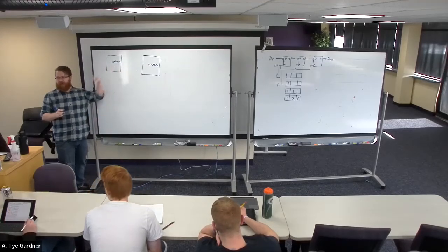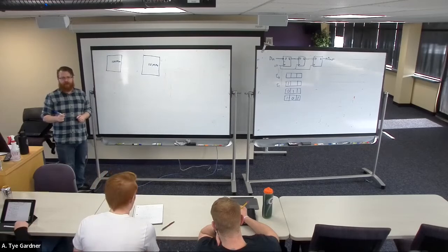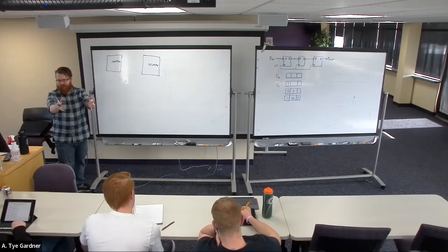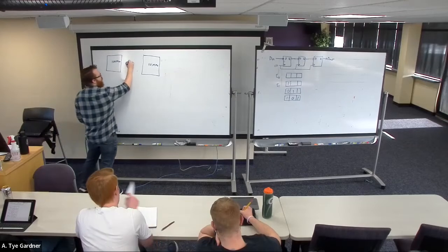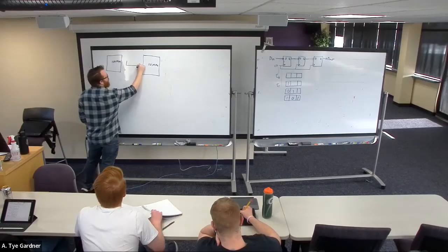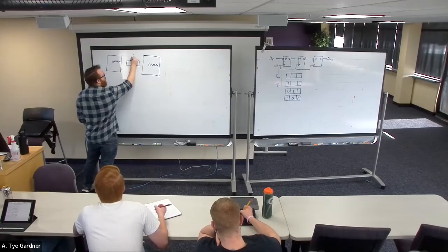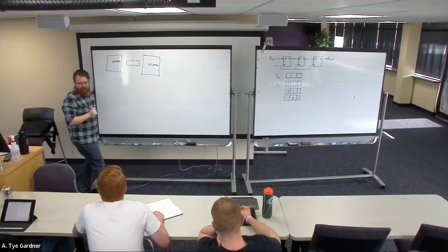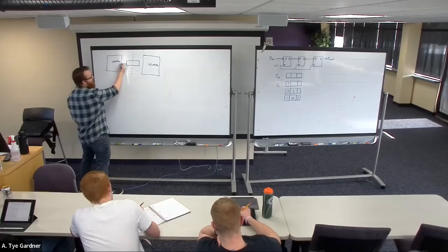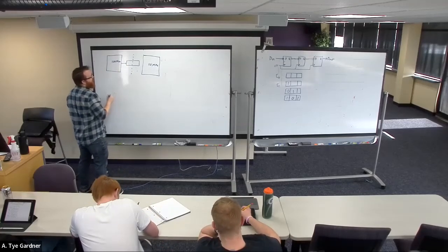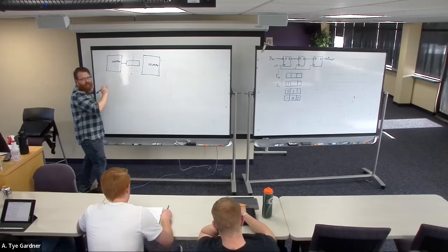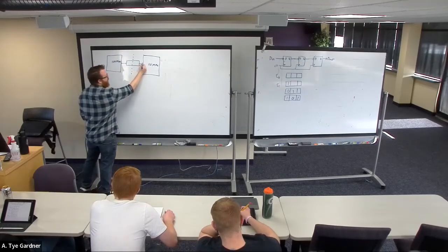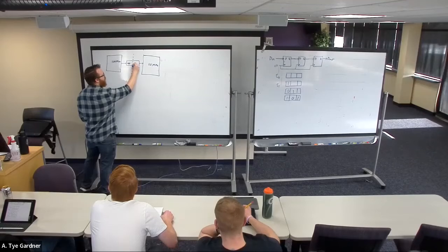But let's say this one comes in spurts. It's like, here's a bunch of data and then wait. Here's a bunch of data and then wait. Well, we could build a device that is a shift register that is going to take an input and queue up at 100 megahertz and transmit out at 10.